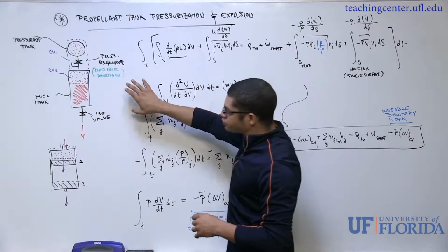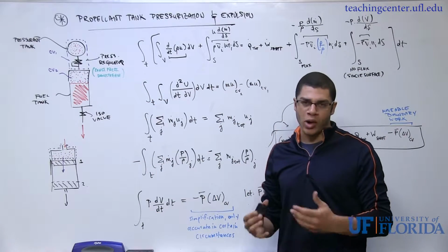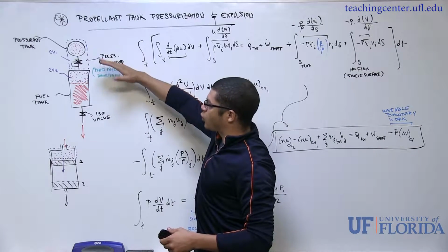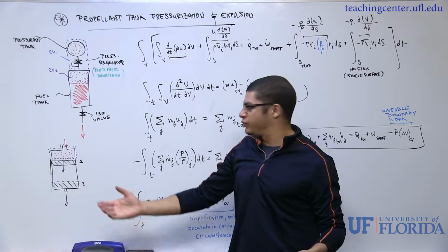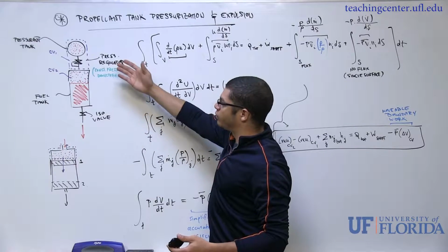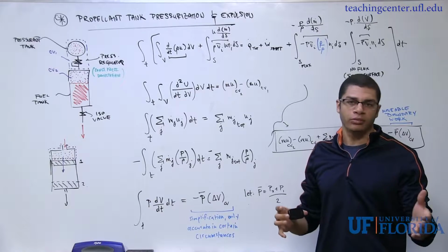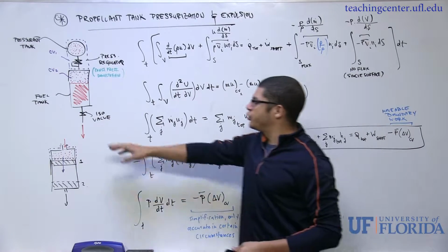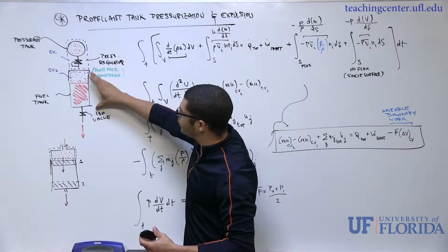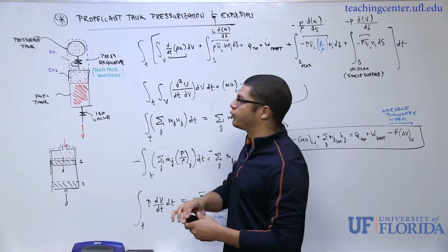So first of all, for a system like this, we may ultimately want to ask, what is the minimum required amount of pressurant gas upstream that's required to push all of this liquid downstream to some process? I've also drawn some other small components in here that may make our lives easier analytically, but also are somewhat practical. Initially, you would have some kind of isolation valve down here before the process begins, and the liquid is likely going to be nearly filled to the top. So that's going to be some kind of initial condition for us.